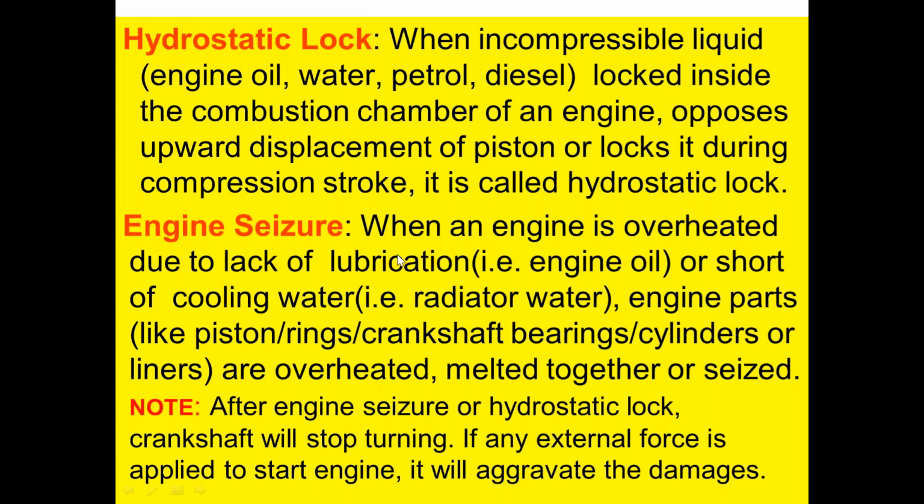Engine seizure. When an engine is overheated due to lack of lubrication, that is engine oil, or shortage of cooling water, that is radiator water, engine parts like piston, rings, crankshaft, bearings, cylinders or liners are overheated, melted together or seized. Please note, after engine seizure or hydrostatic lock, the crankshaft will stop turning. If any external force is applied to start the engine, it will aggravate the damage.